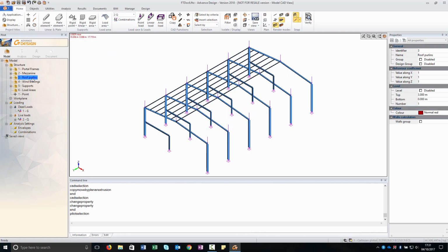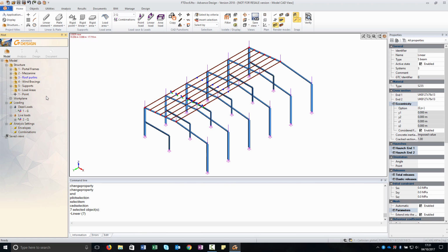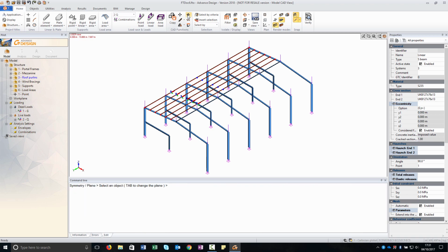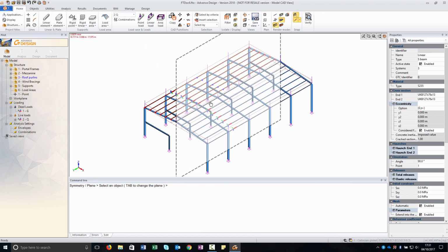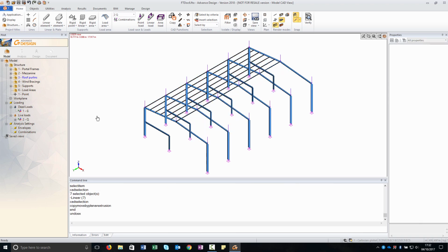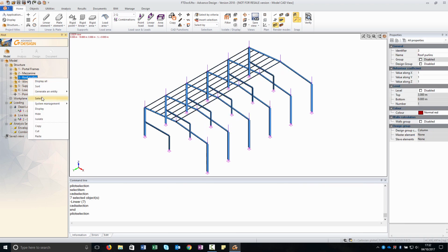You can also use the Symmetry Tool button from the Cut function toolbar in Home to access the Plane Symmetry command. Place the cursor on the top purlin and take it into account as reference element for the vertical plane symmetry. Notice that a preview of the copied element is available. Click to perform the copy of the selected element. If not, you can copy by rotation.